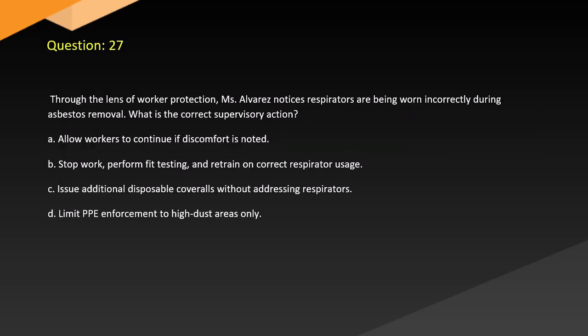Question 27. Through the lens of worker protection, Ms. Alvarez notices respirators are being worn incorrectly during asbestos removal. What is the correct supervisory action? A. Allow workers to continue if discomfort is noted. B. Stop work, perform fit testing, and retrain on correct respirator usage. C. Issue additional disposable coveralls without addressing respirators. D. Limit PPE enforcement to high dust areas only.